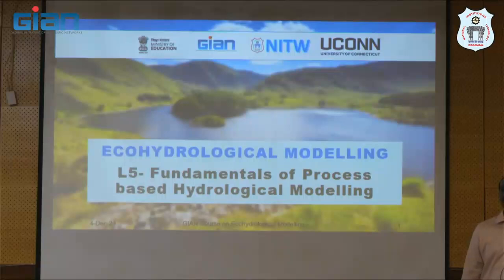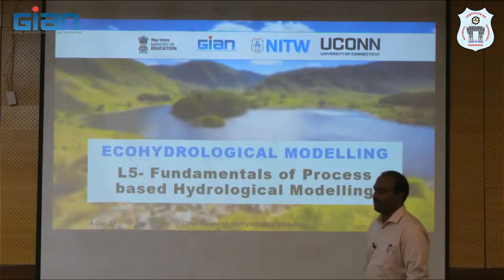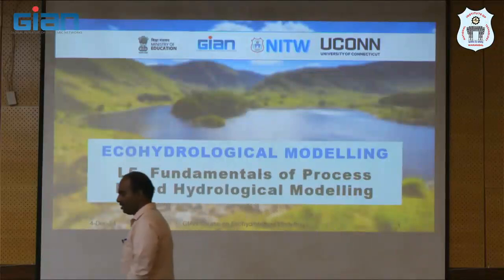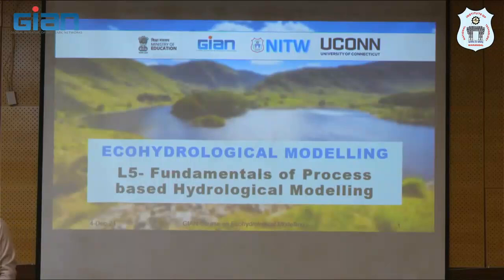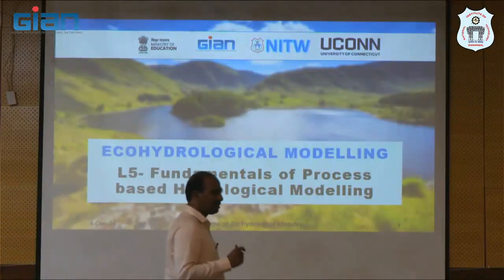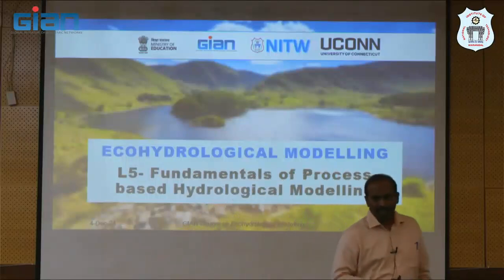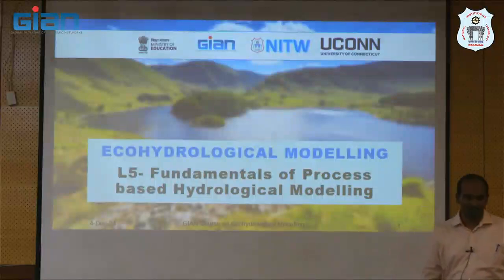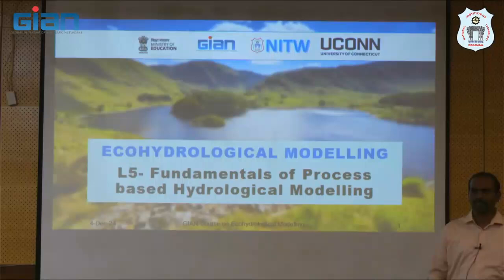So your SWAT model is a combination of mathematical equations. So you see in the hydrological process, runoff, SCS curve number method, it basically transforms the rainfall to runoff through a set of mathematical equations. Penman-Monteith method, it represents the evaporation process mathematically, that given these inputs, you will have this much of an output. Now we have seen them individually. Many of these processes are seen more of in an individual way. How do we combine them to develop a watershed model? Is something that is where the link comes, right?